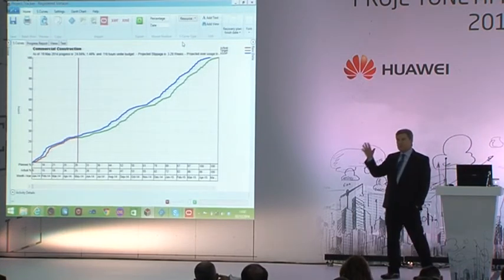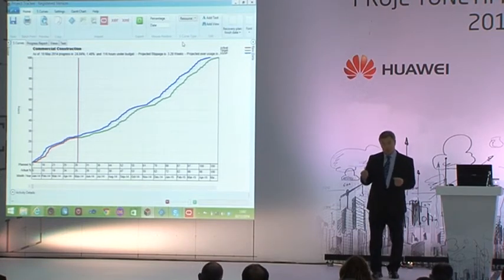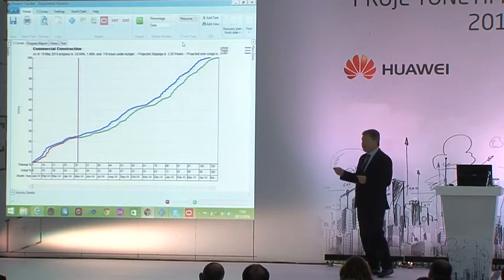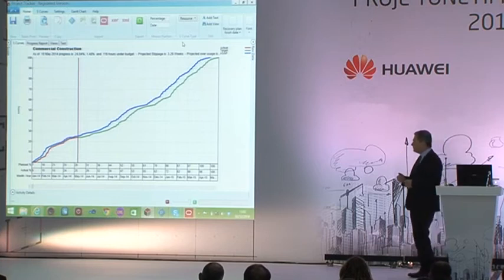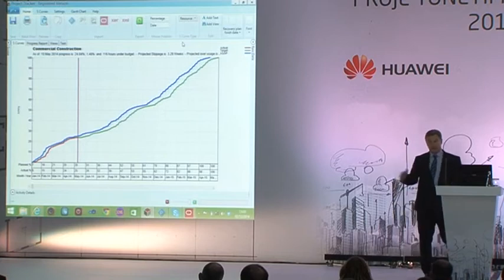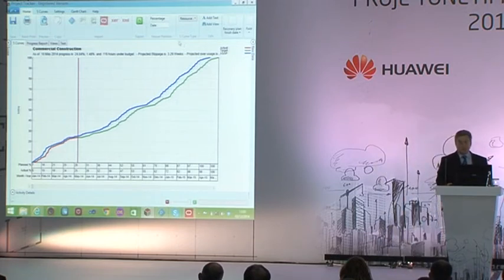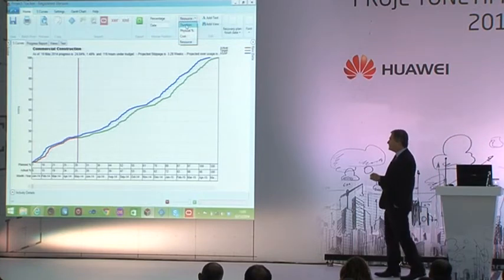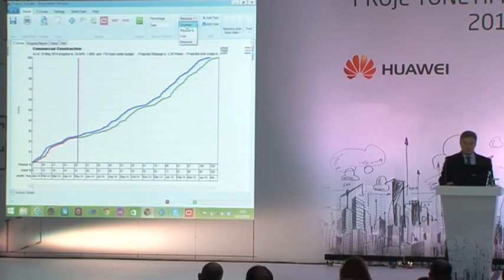And this is on all of the resources on the project, but you'll see in a minute that we can filter down to look at individual resources. And one way that people use this, if you know P6, you can't really do material S-curves, but you can do material curves in here. So you're moving meters cubed of stuff. A lot of people, mining companies, in Australia, like this for the ability for moving material resources. In fact, you can do physical percent complete as well. So if you use physical percent complete rather than duration percent complete, you can curve that as well.